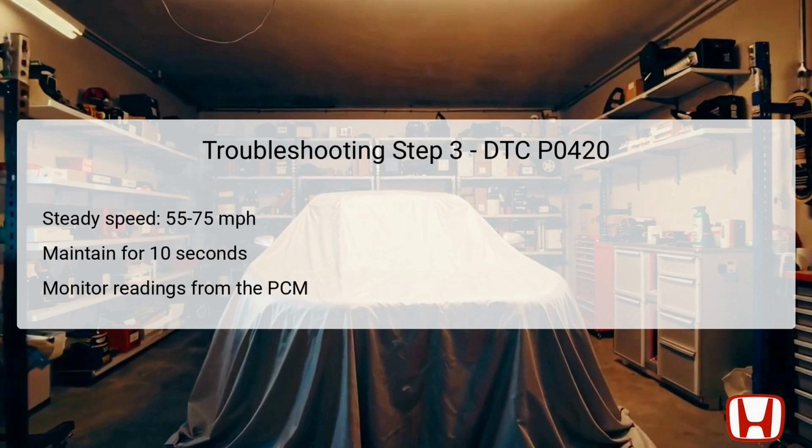For the third step in troubleshooting DTC P0420, you need to drive at a steady speed between 55 to 75 miles per hour for at least 10 seconds. This phase is crucial for allowing the Powertrain Control Module, PCM, to gather consistent data from the secondary heated oxygen sensor, HO2S, about the catalytic converter's efficiency.